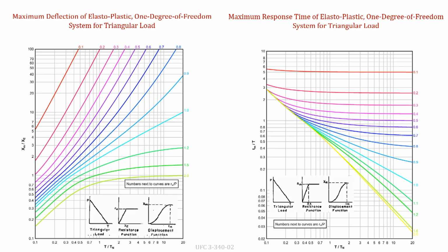So, here we are calculating the response of the system using the same approximations. T is the time period of the loading, Tn is the time period of the structure, and here we are using a curve of Ru divided by P.